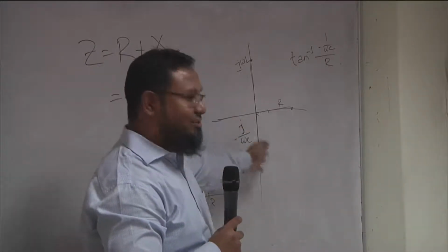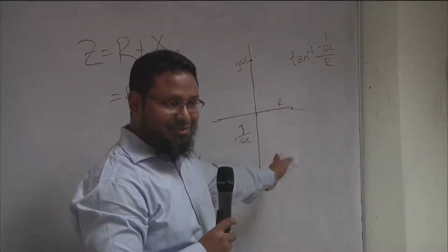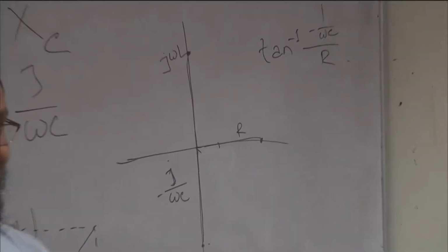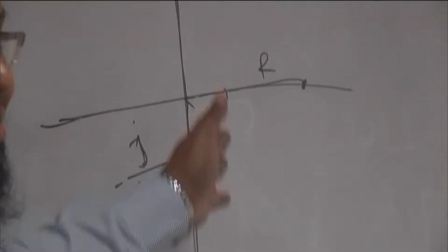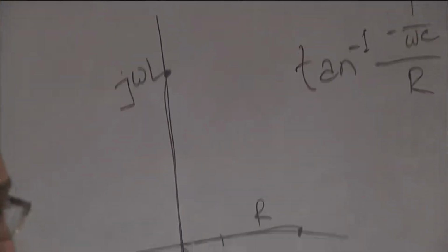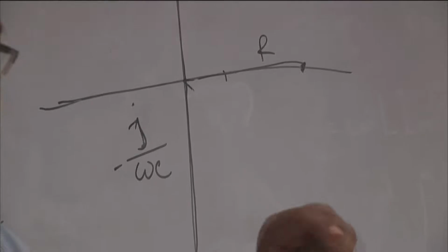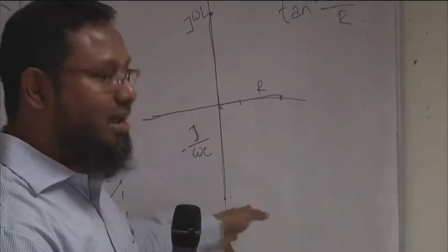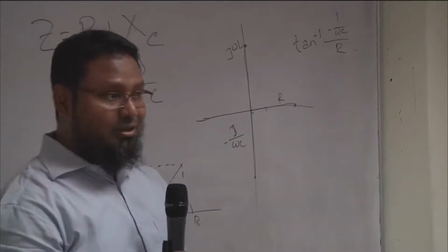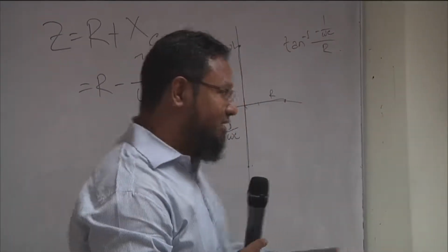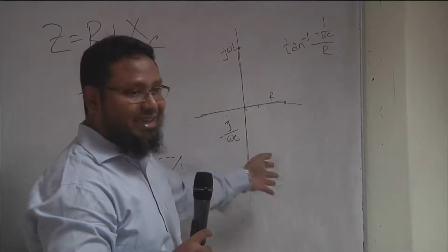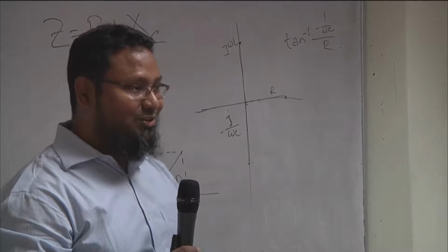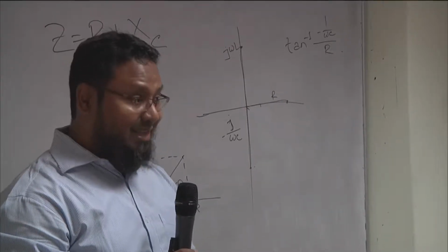Of course, the first thing you'll notice is that these reactances, or the imaginary parts, will cancel each other out. Not entirely though, depending on which one is bigger or smaller. You will end up having a little reactance, either in the positive or negative direction, depending on their magnitudes. But a very specific circumstance may happen where they cancel each other out equally and the whole reactance becomes zero. That's possible as well.